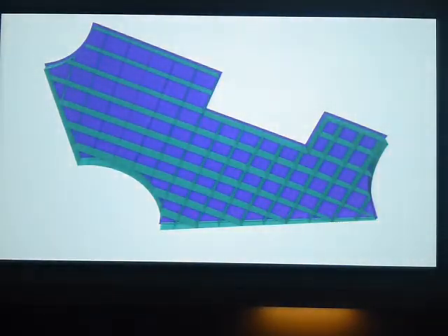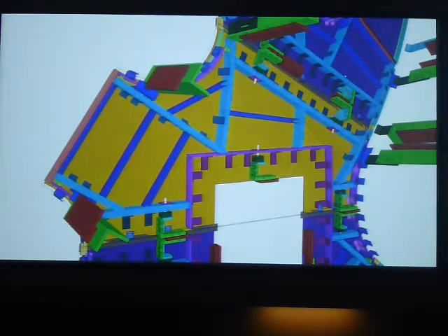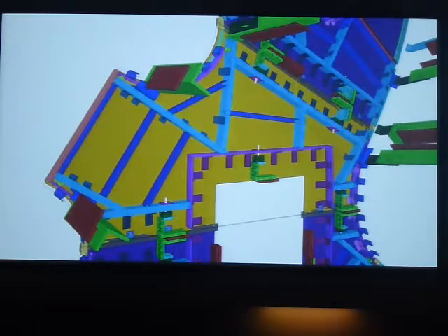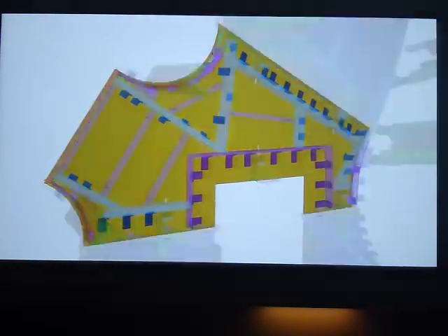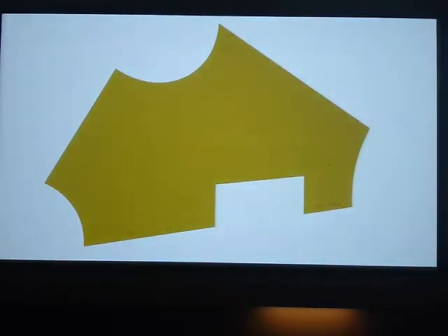The sheets are CNC milled after they have been welded to a CNC milled template. The template files are provided by us as 3D models of single surfaces. And the position of all elements is determined by the studs that are welded to the aluminum sheets. The locations of these studs need to be CNC defined. Therefore, we have to provide the locations as coordinates. But for verification purposes, we also need to produce a dimension drawing for each sheet showing all stud locations relative to the sheet edges. Then we take a few steps to find all these stud locations on the panel.